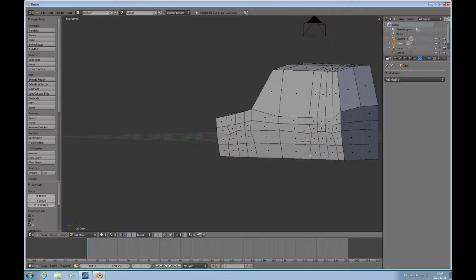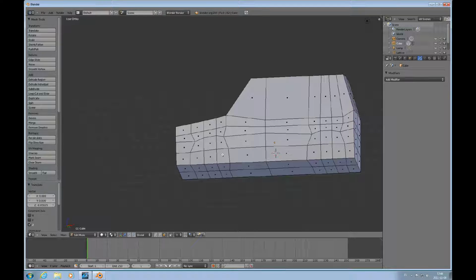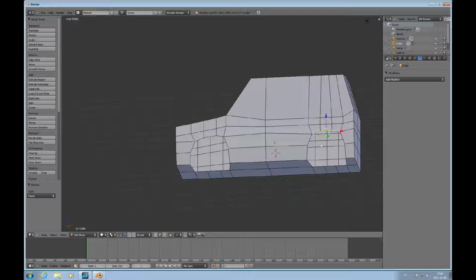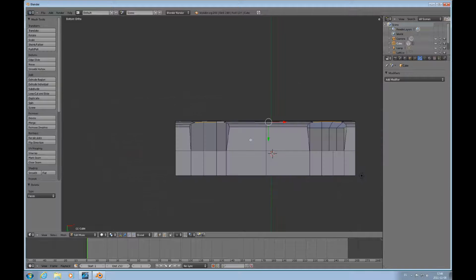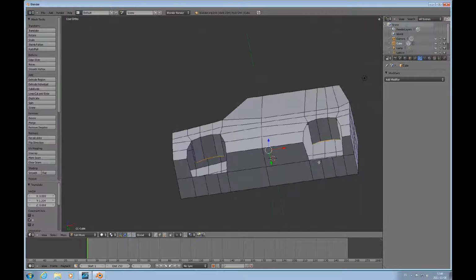Okay, let's move on. And control left mouse button to just lasso these ends. Delete those faces, and then go to edge mode and select these, the upper ones here, and do Control 7 to look at it from the bottom, E for extrude, and pull these down all the way to here. Then we can try this, see if this works. I'm going to attempt to bridge these two at the same time, and it worked.